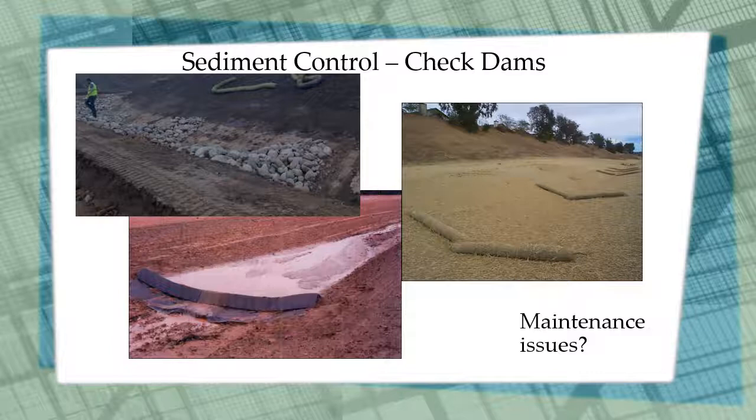The check dam on the bottom left is working really well, as evident by how much sediment is deposited upstream of the check dam. But it needs to be cleaned out. Like all BMPs, check dams work best when they're maintained properly.